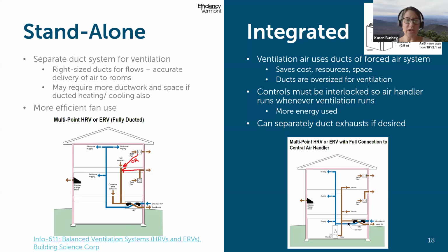It's going to require more duct work and more space, obviously, for two completely ducted systems. And so that's one of the drawbacks, as well as the material that you're using to make those systems. And one of the big benefits that I see is that you don't need to run your air handler year round like you would in the other type of system.